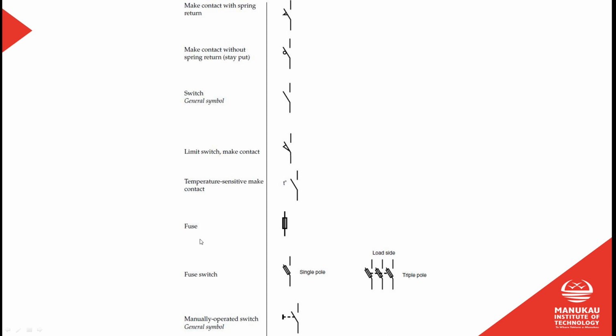So I was talking about the fuse, and I just said that when I'm making basic electrical drawings, I would use that fuse symbol as a generic symbol for any sort of circuit protection. If you threw that down to say there is some sort of circuit protection here, whether it's a circuit breaker, fuse, whatever, you would usually use something like that.